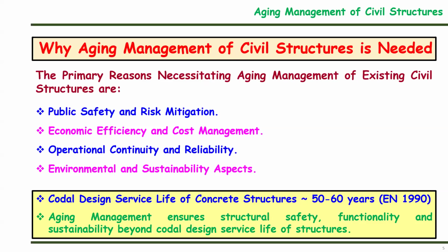Okay, now if we look at Eurocode EN 1990, as per the Eurocode, the design service life of concrete structures is about 50 to 60 years. So if we have a proper aging management plan, then that plan will ensure the structural safety, functionality and sustainability even beyond the codal design service life of the structure. So this is the main reason why we need an effective aging management program.